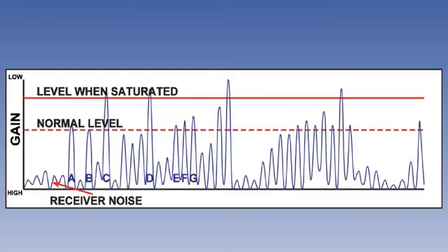The effect of this is to exclude the transmissions from aircraft whose interrogation pulses are weaker. Here, we see that aircraft A to G are receiving ranges from the ground station, with B just entering the coverage. When the transponder becomes saturated, the transmission intensity is reduced, so that aircraft A, B, E, F and G will be excluded and unlock. This gives preference to the aircraft with the strongest signal, in this case C and D.